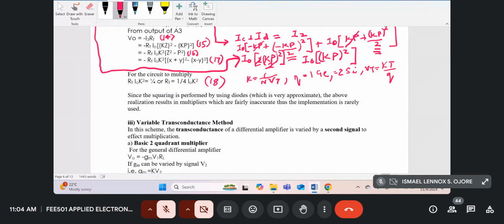So this scheme over here, and in fact I could have added some more over there, you can see how many op-amps are used over there. And all the op-amps are going to be suffering from offsets. You have to have null offsetting circuits for all the op-amps. So it's going to be a tedious way to try and multiply two analog signals. So this implementation is just academic, because we're trying to use the identity, but practically it's impossible to design a good multiplier with high accuracy using this scheme.